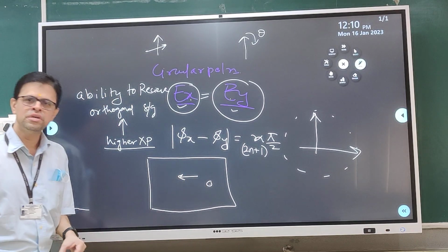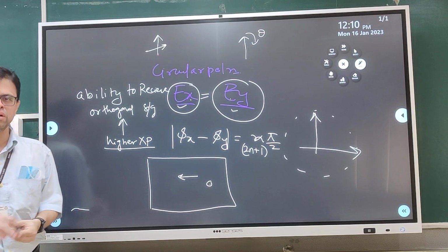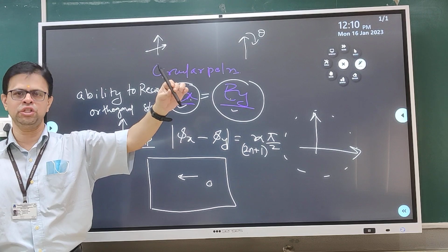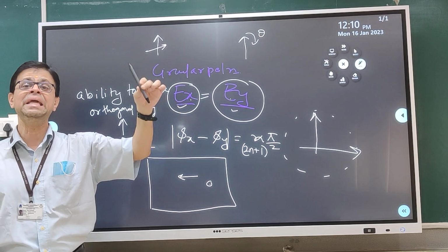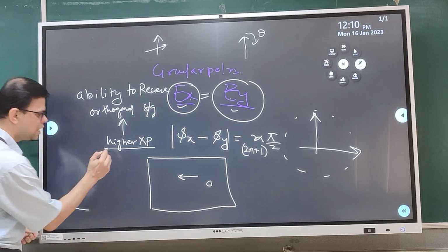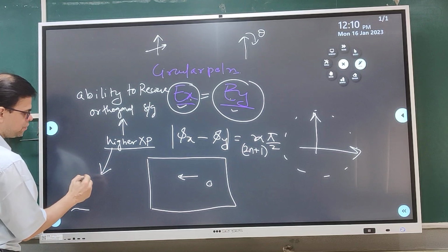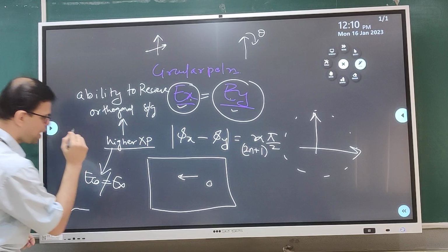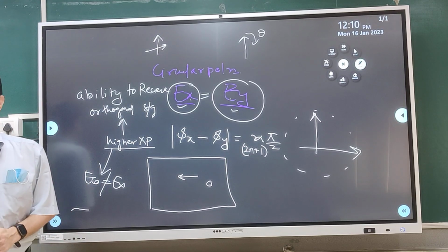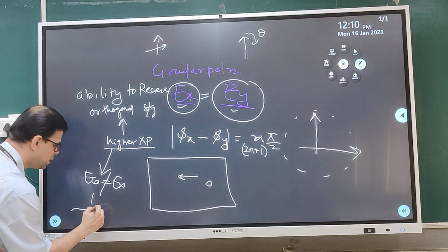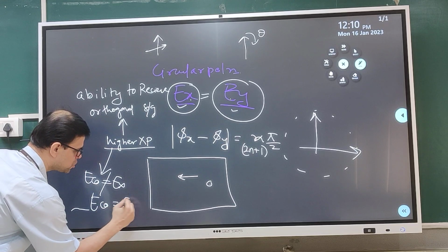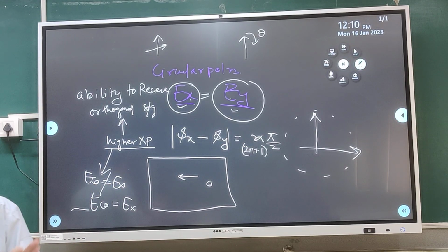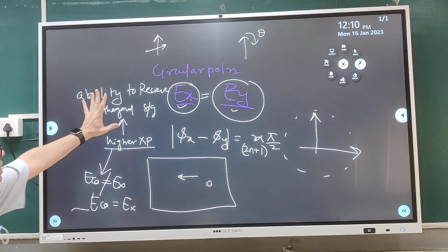So in case of circular polarization, what I want is, let the antenna be like this, let the antenna be like this. In both the orientations, I should get equal power. Which means that the co and cross polar components are not equal in a linear or elliptical polarized antenna, but the co and cross polar components are nearly the same in CP designs. So this is something very important.